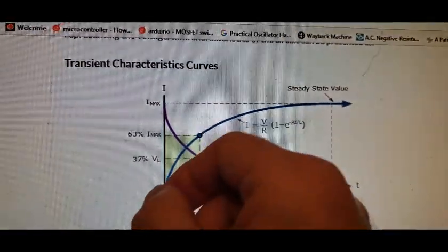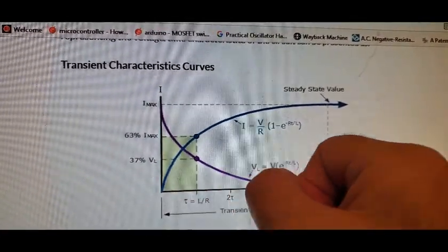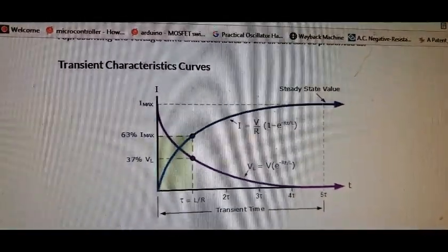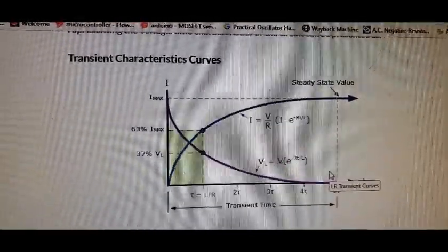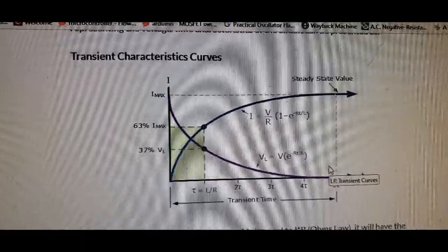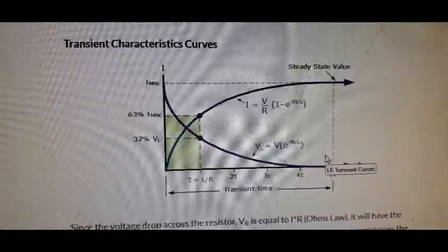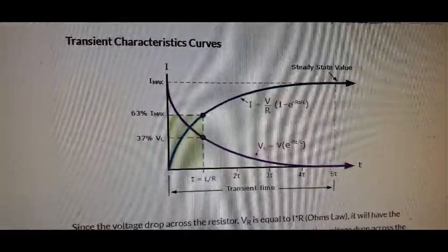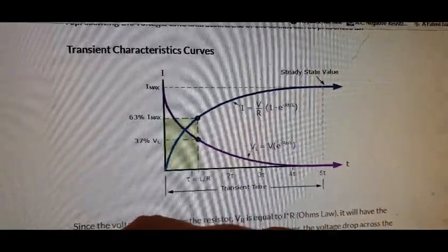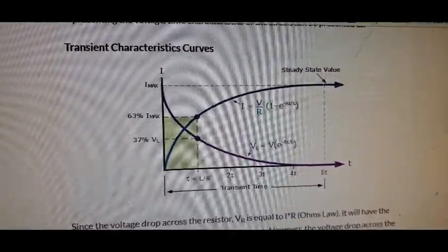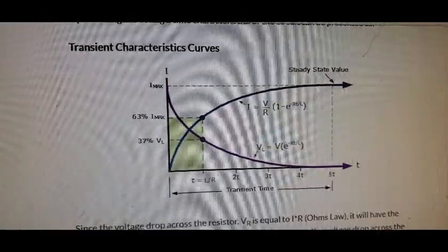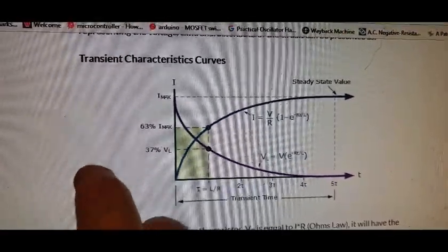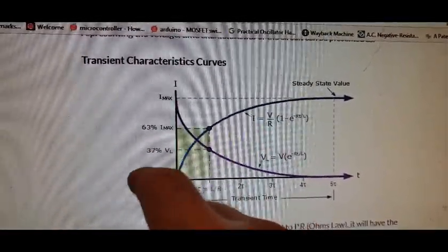You know, do they go fast enough, or do they change at different speeds, or of course skin effect. It's a big one with the air core. And then if you're not using an air core, if you're using a ferrite core or something like that, then you run into a whole slew of other issues. And we can just group those all together as core losses, and note that some of the core losses often seem to change not linearly, but by a power of 2 or 3, depending on things like frequency and current.